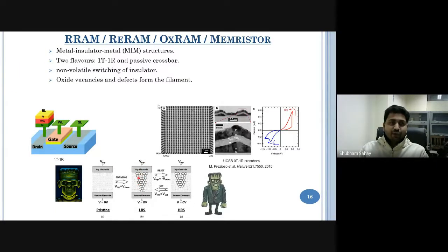And in soft breakdown, what happens? Oxygen vacancies are created. So once oxygen vacancies are created, there is something which connects the top electrode to the bottom electrode, and through that, electrons can flow. So its resistance decreases. Now, when you apply a negative voltage on the top electrode, you essentially pull some of these vacancies towards itself, and as such, some of the insulator region is uncovered. So once the insulator region is uncovered, then what happens? The device again goes to the high resistance state.